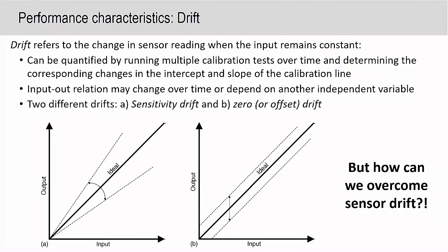Yep. So this basically means putting a sensor into the patient and then working out what the real value is. So having, for instance, let's say we're measuring blood pressure in the patient using the implanted sensor. What we can do is, if we think it's drifted a little bit, we can take another sensor outside the body, calibrate it, insert that into the body, and then see how different they are, and then adjust the transfer function. Just one, as long as it's one sensor that we know is accurate,